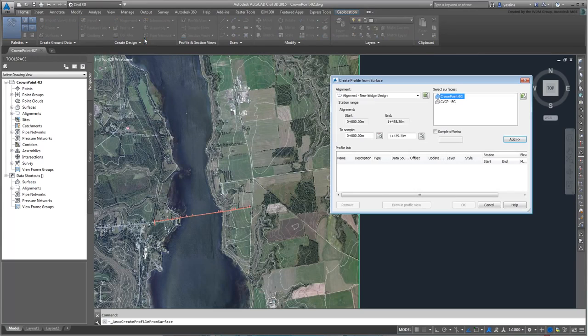You need to specify an alignment to use as a cross-section. You only have the one you created in the last movie. That's the one you need. You also need to specify a surface to cut across. There are two to choose from, even though they are essentially duplicates, albeit with one that has less detail than the other. Here you can choose either one. It wouldn't make a big difference. Note that even though the original surface is hidden from view, you can still use it as reference.